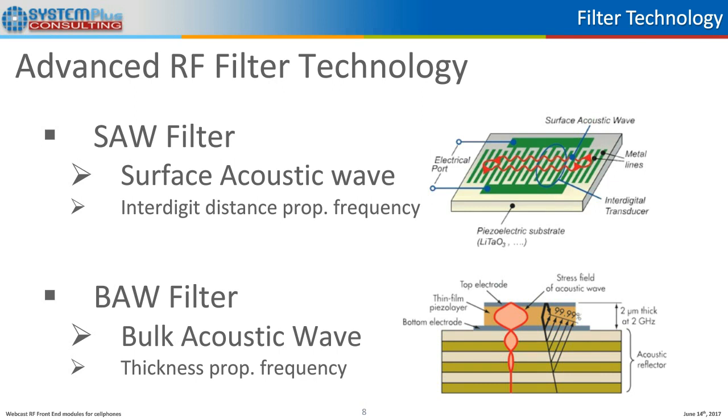The acoustic wave will travel in the piezoelectric layer, deposited on an acoustic reflector. So technically, the limit of this technology is the thickness of the piezoelectric. So the integration could be better in high frequency.